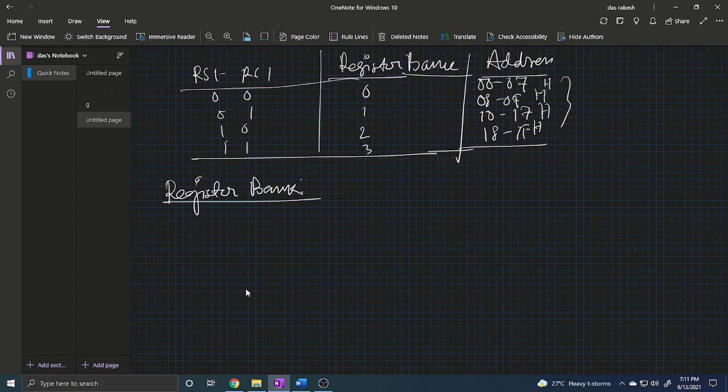A register bank is a bank where we store data permanently or temporarily, and copy and paste operations are also available for this bank. But there are some restrictions, because the 8051 microcontroller has a total of 128 bytes of RAM. First of all, note it down. There are basically some steps followed. First of all, a total of 32 bytes from 00 to 1F. So the first 32 bytes, 00 to 1F, of RAM are assigned for the register bank and for the stack. This is very important.